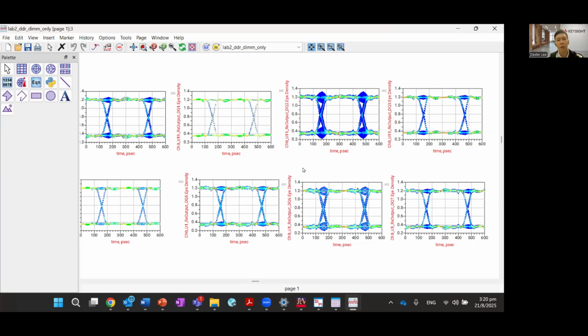Hopefully from here you can see that in ADS we do have this kind of smart component to represent multiple transmitter and multiple receiver models, and then the smart bus wire to have just one wire for you to connect everything up together. This helps you to be efficient, and less confusing and less complex when it comes to this kind of simulation setup.